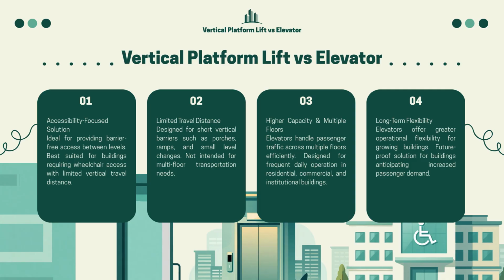Conclusion. So, vertical platform lift or elevator? There is no universal answer. A vertical platform lift can be an excellent solution when the main goal is accessibility, the travel distance is limited, and installation space is restricted.